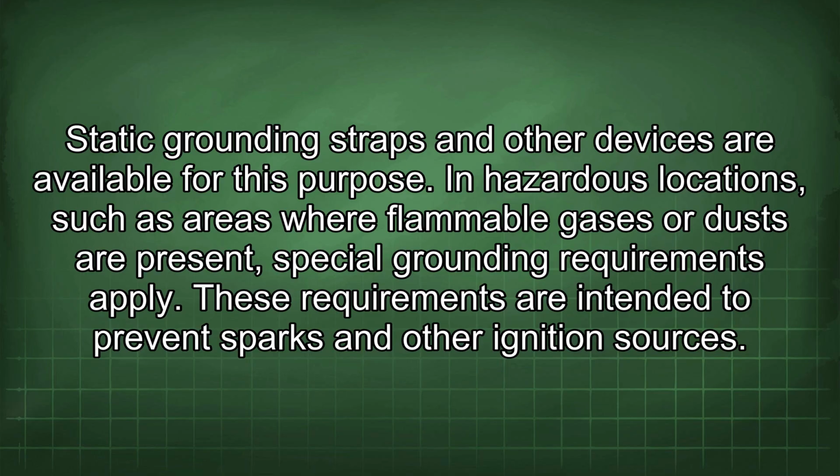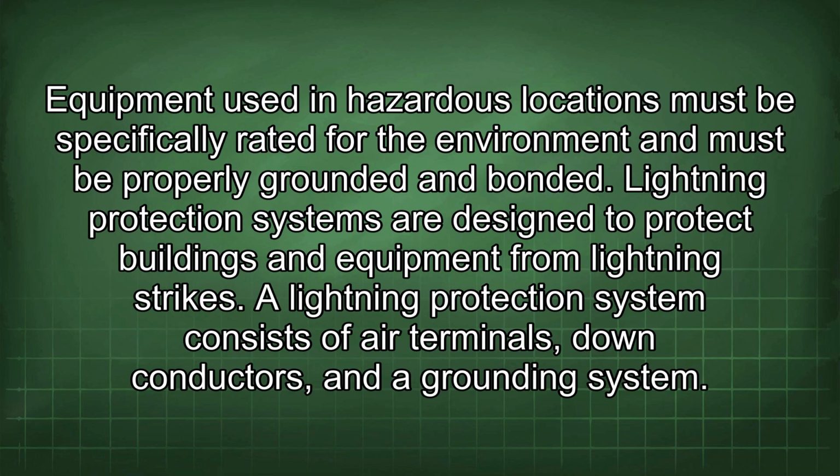In hazardous locations, such as areas where flammable gases or dusts are present, special grounding requirements apply. These requirements are intended to prevent sparks and other ignition sources. Equipment used in hazardous locations must be specifically rated for the environment and must be properly grounded and bonded.